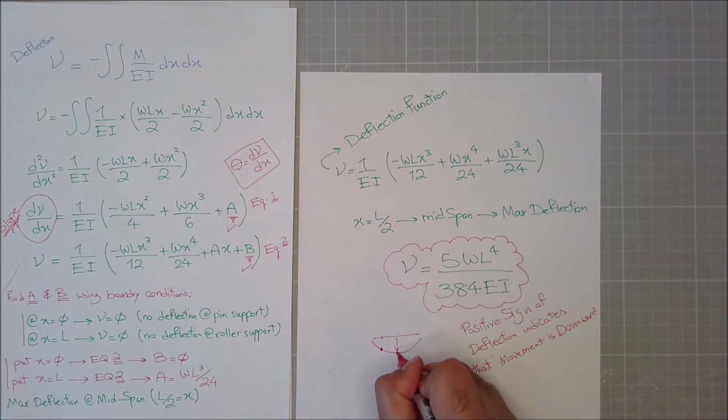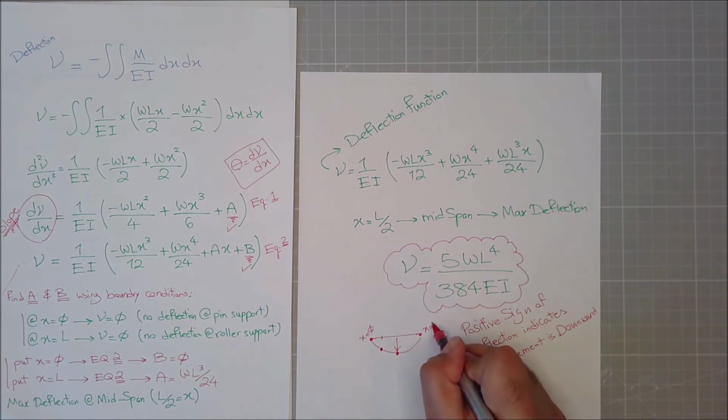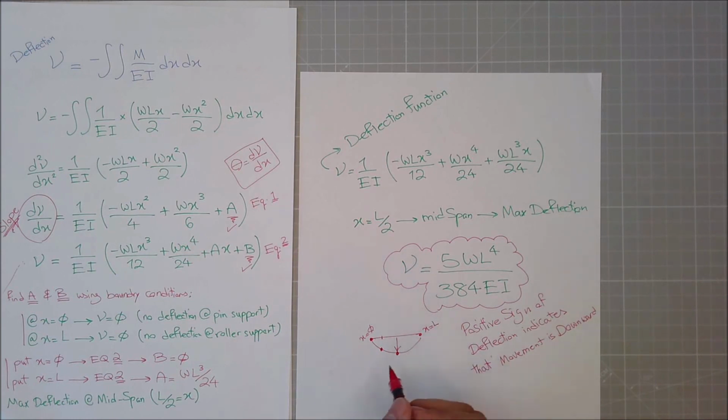We calculated what is deflection here. Trust me, if you put x equal to 0 or x equal to L, you'll get 0 deflections. As we discussed, due to the boundary condition as well, deflection here and deflection here will be 0. Deflection at the midspan will be maximum. What is that maximum? That's where this is equal to 0.